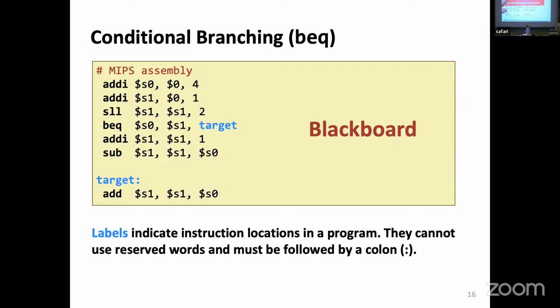I'm doing more or less the same in the next one. I know, you see, this is the point. It looks pointless. It looks like I'm doing an operation just to move this thing. That helps me keep the number of instruction types down. If I want to move a constant to a register, I can just add immediate to register 0 the constant. And since register 0 is always 0, I'll add 0 to a number and write it to the register, so I don't have to make 2 different types of things.